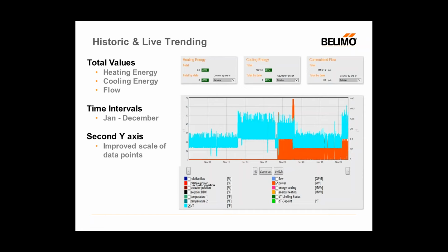And one other thing we can do here on this screen is overrides. So if you choose to override, we have 9 different override settings that you can put the energy valve into. You can go to wide open, fully closed. You can stop the motor in place. You can go to what we call VNOM, the nominal or maximum rated flow value of the valve. Vmax, which is your programmed flow rating of the valve, which for those of you who don't know, with an energy valve, you can program your maximum flow rating down to 30% of its nominal flow or its maximum design flow rate.